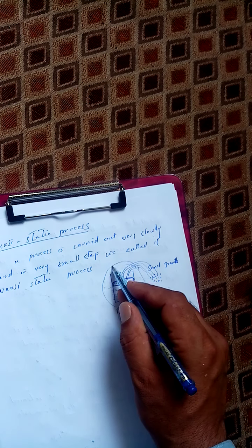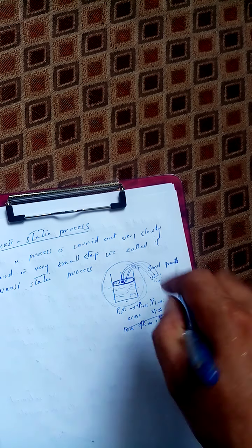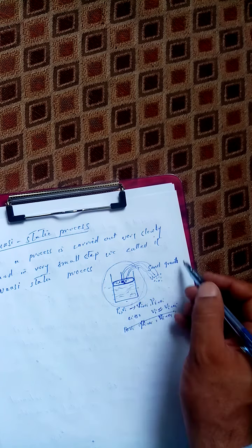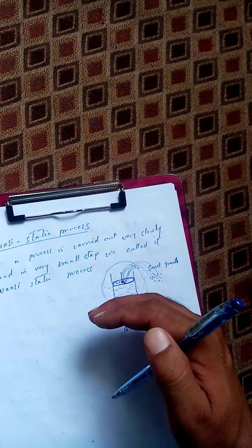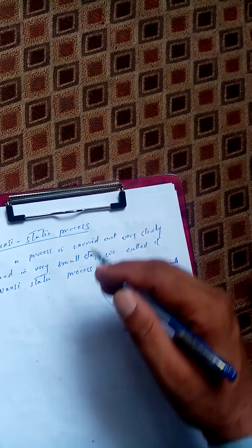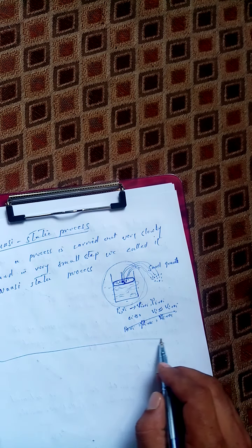So in a quasi-static process the system is always in equilibrium, and also it is reversible. Suppose we put a grain here, another grain of sand here, and another here, so the piston moves down very slightly, but if we remove the grains then the piston will move up. So this is a reversible process also. This is all about quasi-static process.